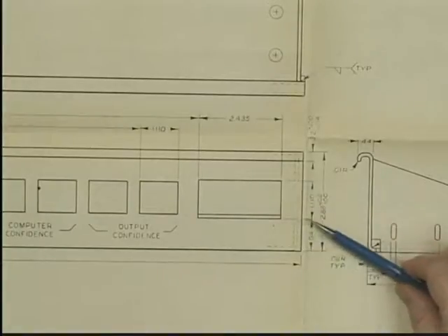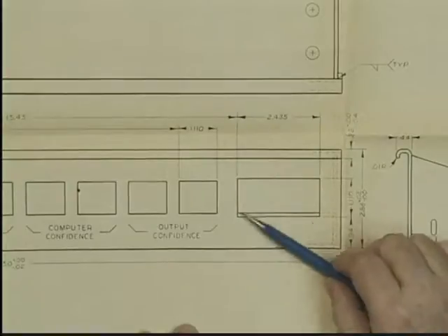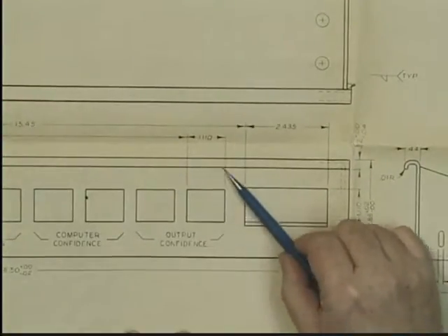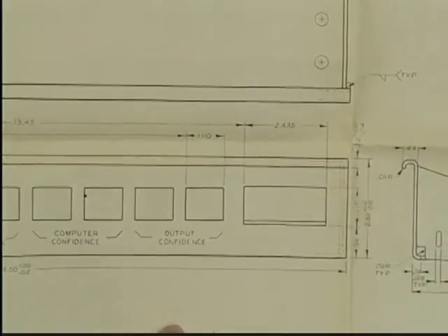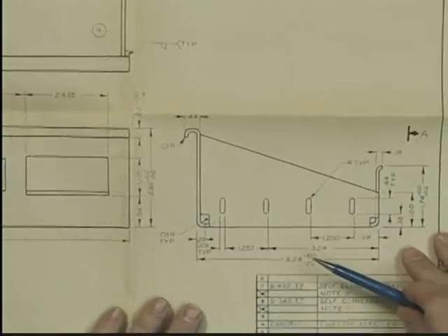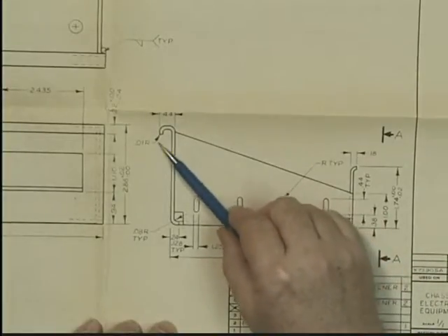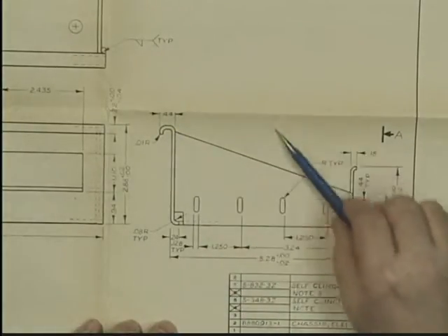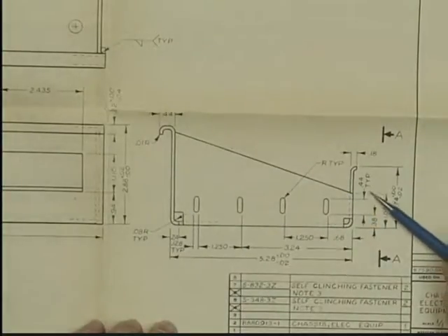Now this drawing is a lot bigger than we have room for in this little television set right now, but if we zoom out on the whole drawing, you won't be able to read anything. This is actually a drawing of the sheet metal chassis, and you notice that not only is the shape described by this picture, but the size is described with these dimensions. If I show you over here on the right side view, you can see that this is made of sheet metal, has this nice little hook here, and the front cover actually latched around that so that it would be very clean on the front, and we only needed fasteners on the back.